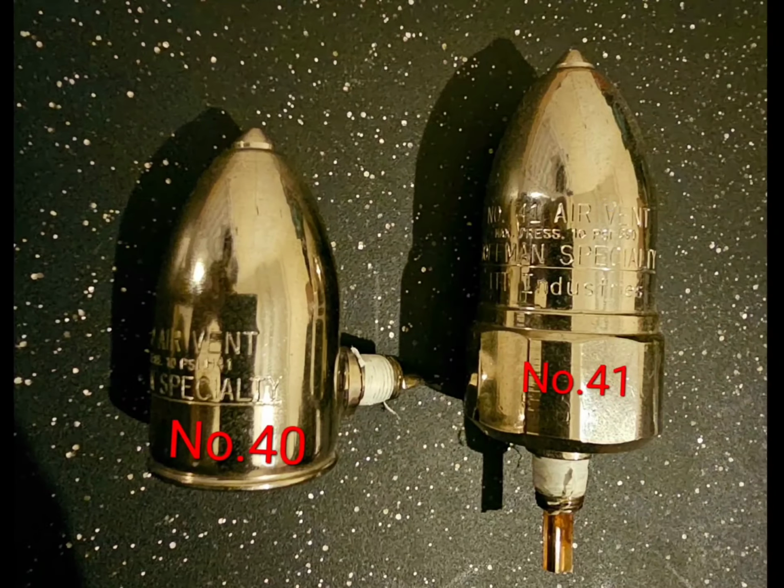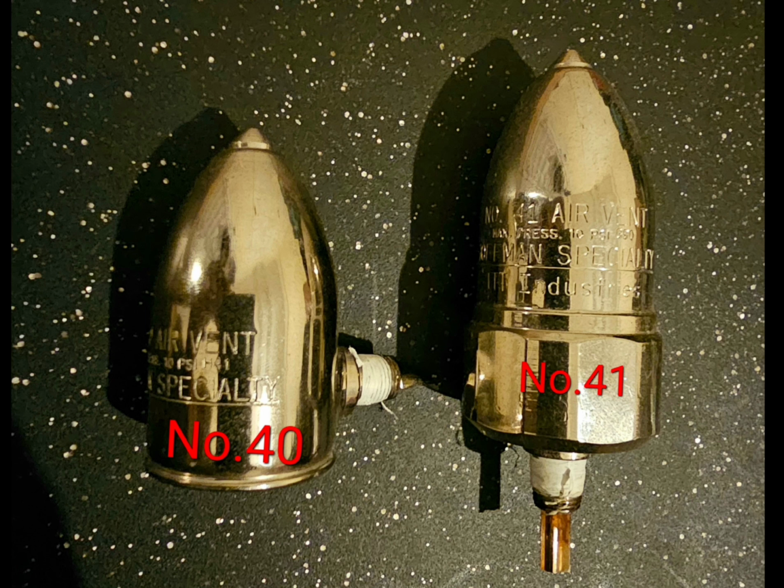So let's go back into the Hoffman vent. Steel convectors don't hold the heat the same way. So they'll heat up fast, and what you notice is that thing will start heating up, and if you have a good air vent on it, it'll stay hot. And how it'll stay hot, you will periodically hear that vent opening up to allow cold steam out and fresh steam back inside the radiator. That's how it's going to stay hot.